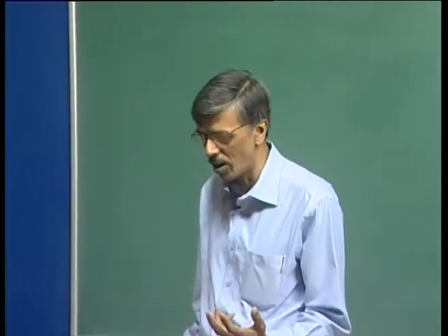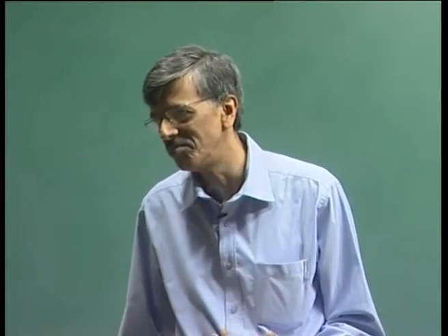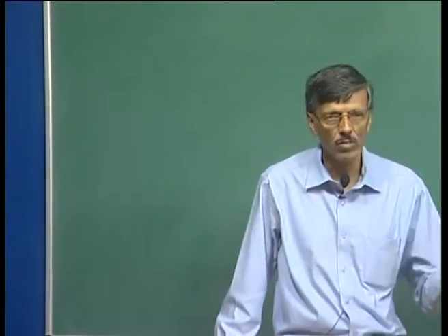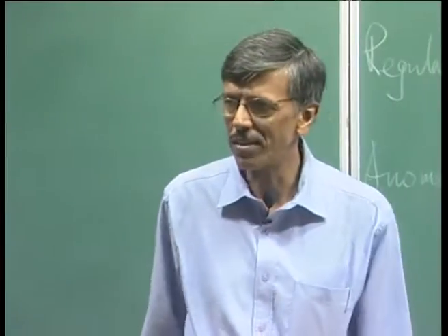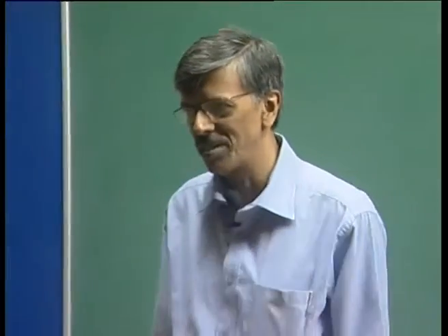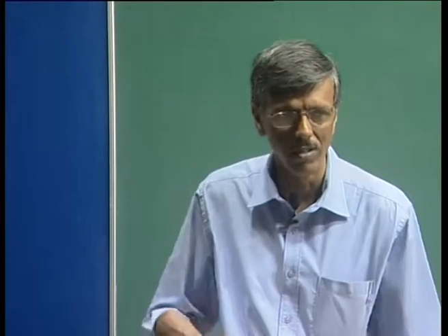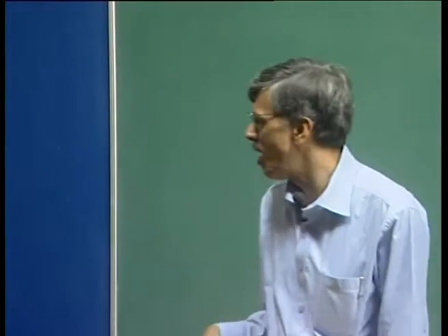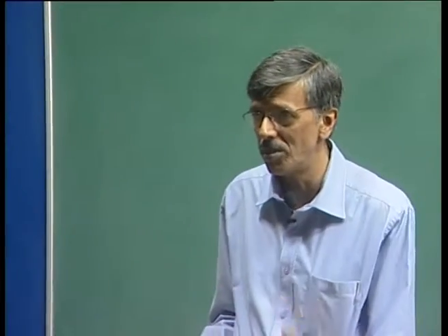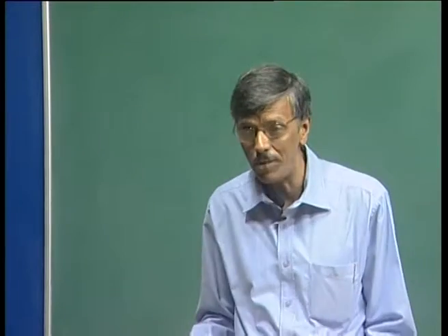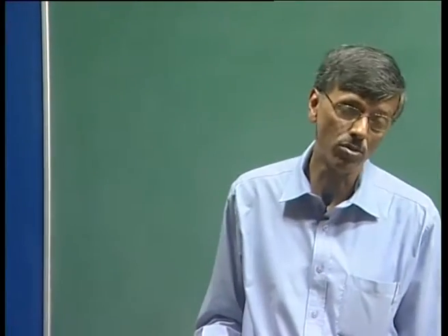See, that is why in this course, although it is titled Transition and Turbulence, I have spent most of my time talking about the transition aspect with the twin object. One is, of course, all these phenomena are instability driven, and number two is to basically fight the ghost of the commonly held perception that turbulence is universal. So, it does not matter how you get there, it will all be given by a single model, which is not true. We firmly believe, some of us firmly believe that there is multiplicity in the point of view of the turbulent flow itself, and what end product you get depends on which route you have traversed. And which are the routes? These are the routes of instabilities.